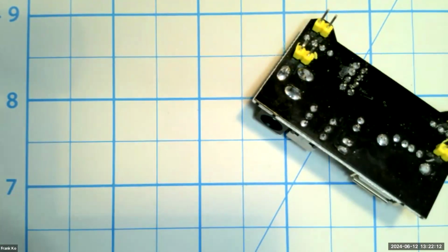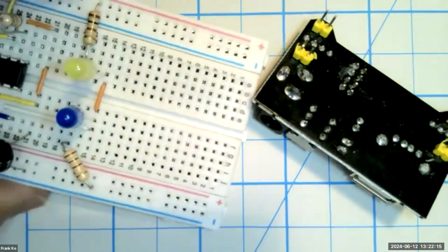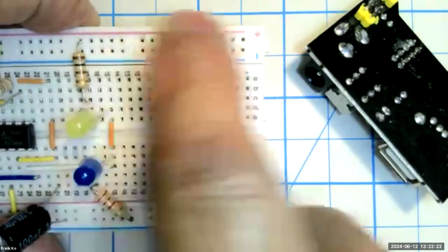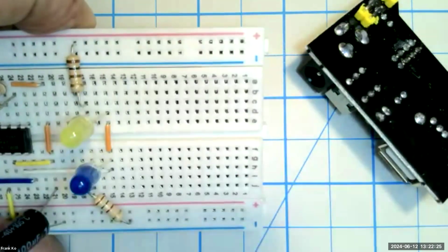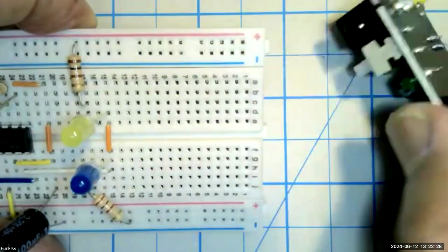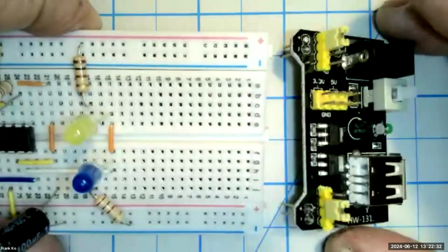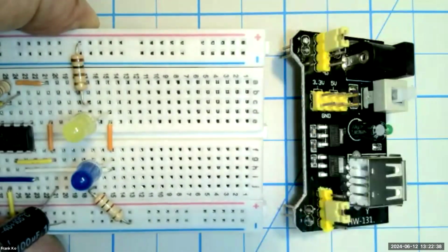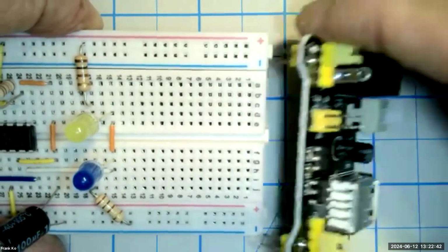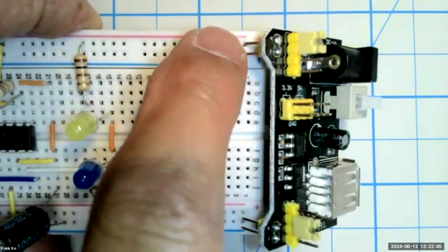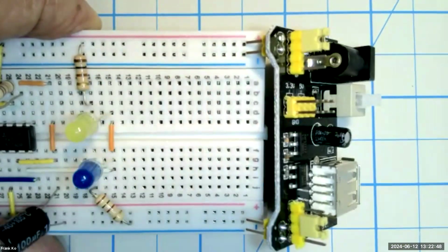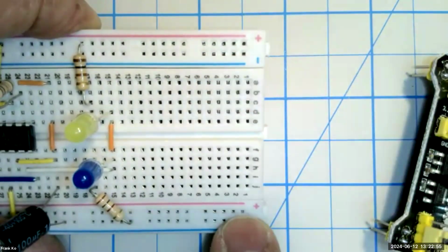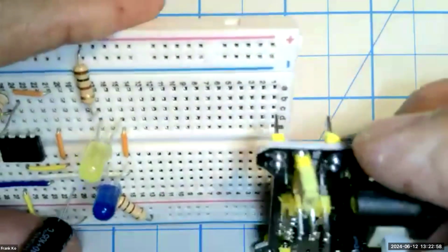What we're going to do is now we're going to attach this to a breadboard, and I'm going to recommend, for the sake of consistency, that we set up our breadboards with the red stripe, the red power rail, away from you at the top of this illustration, because what we're going to do with our power supply is, since we've already set this up to be 5 volts, you can see that I have the plus and the minus terminal of these first 2 pins that will be connected to the positive rail and the negative rail. Now, the most secure place to mount this will be in the very first set of points right here. They align very nicely with your power supply.